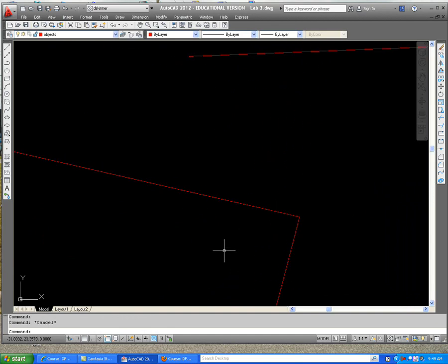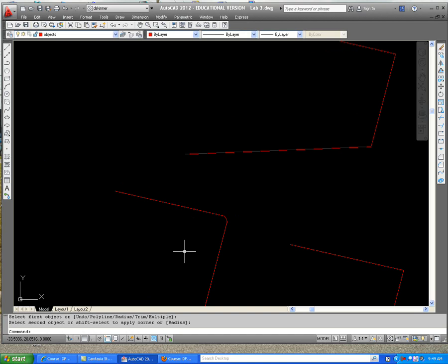And go to this one. And I'm going to do the fillet command again. Like I said, it's over here. And also if I type F and hit Enter, it brings up fillet. Now since 0.25 was the last one that I used, that is still in there, but I'm going to type R. I'm going to make a bigger radius. Now it didn't show up that well. And then I'm going to click here and here, and then it brings a radius in there for me.